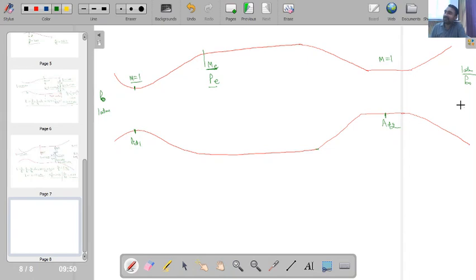So if you see, ideally here also I am having 1 atmospheric pressure condition, here I am having 1 atmospheric pressure condition. So the pressure ratio required for this section is 1. It means no pressure is required at the inlet, or no vacuum is required at the outlet to create the flow. So I can say that this type of combination of nozzle and diffuser is a perpetual motion machine. You just place it in the ambient, here you have atmospheric, the other end also atmospheric, and inside you will get a supersonic situation.